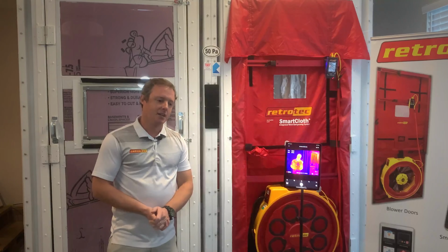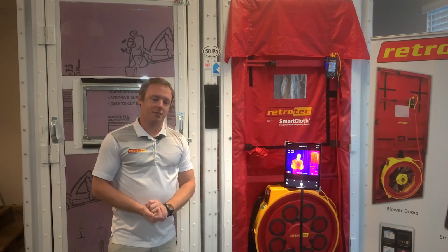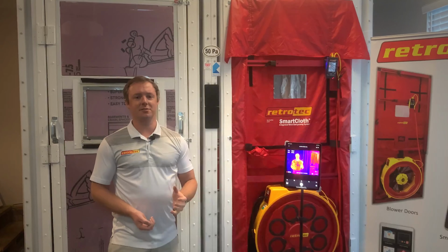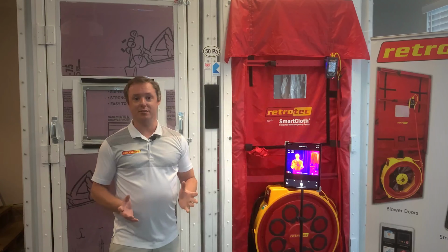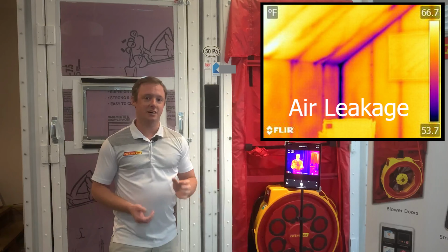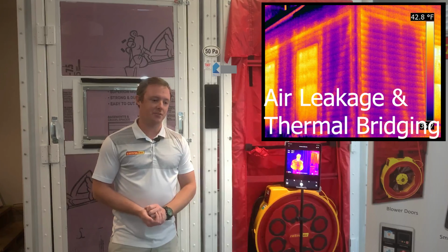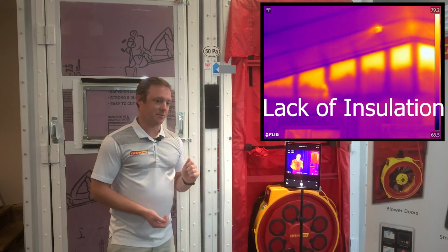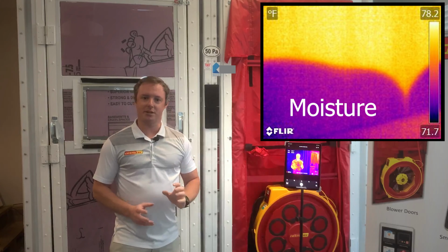And one thing that I always recommend, if you're going to really apply this stuff to your daily work, is to try and get at least a level 1 thermographer certification. It's one of the best ways to get some good education on how to use your thermal camera and how to interpret what you're seeing. Because it could be a number of things. If you see a discoloration in a wall assembly or a floor or a ceiling, you want to make sure that you know if it's air leakage, is it thermal bridging, is it moisture? It could be a number of things. So you want to be able to tell one thing from another.